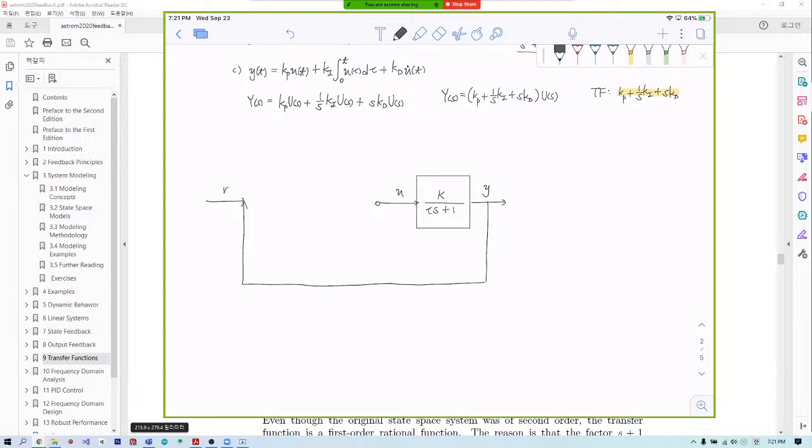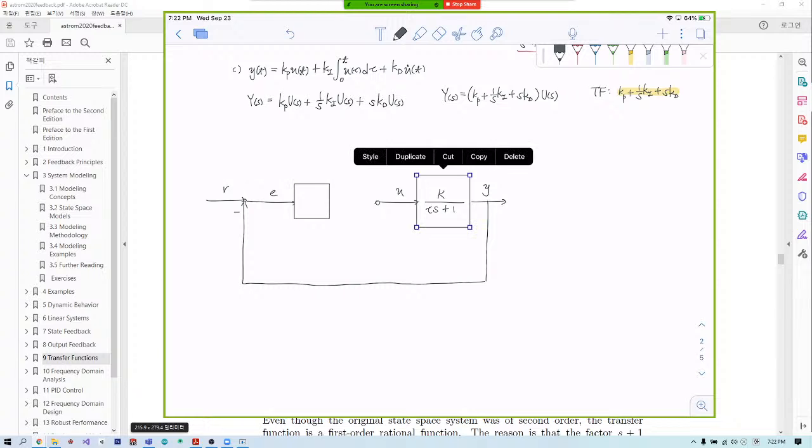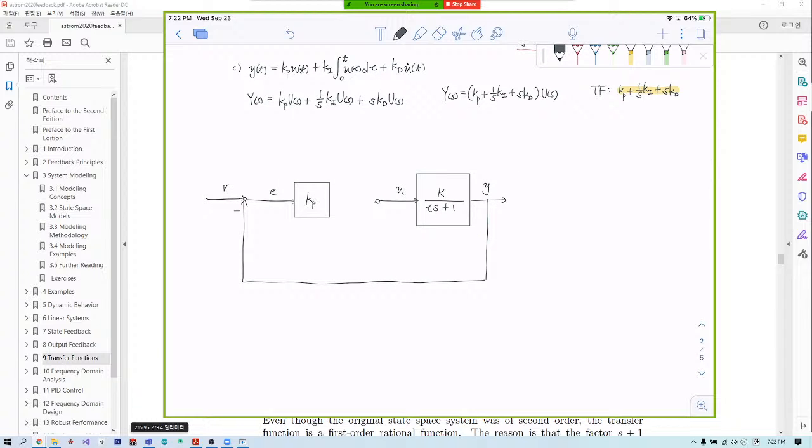And the difference between the desired reference value and the current value is compared, and we subtract what we have for now from our desired value. And what's going to be left? We're going to have an error, because error is defined by the difference between what we want and what we have. Okay? And the first thing we do is multiply our error by the proportional constant.